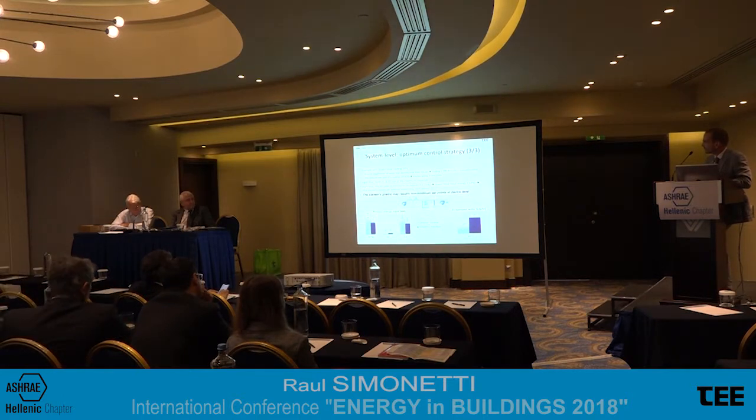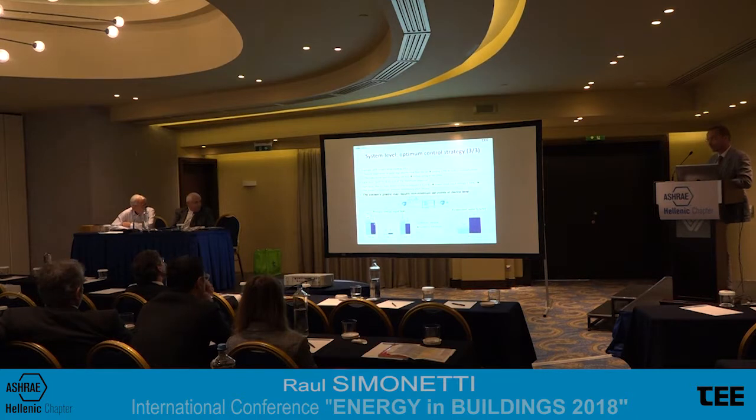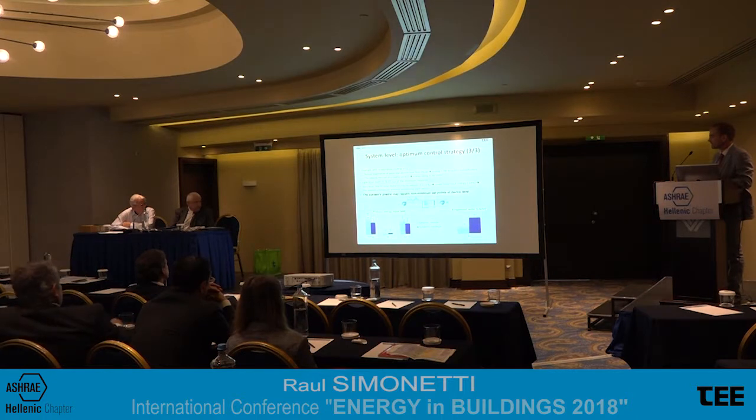If you displace their duties and increase the sprayed water, and so the cooling effect of the evaporative cooler, it will consume a bit more energy, from 34 kilowatts to 39, but at the same time the cooling coil will decrease its duty from 385 to 304 kilowatts, and therefore the sum will decrease from 419 to 343. Of course, you will use a bit more water, but the final result will be that while still guaranteeing the set points of humidity and temperature, you will save energy.